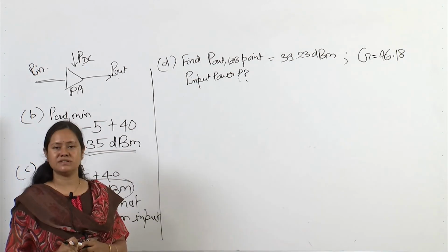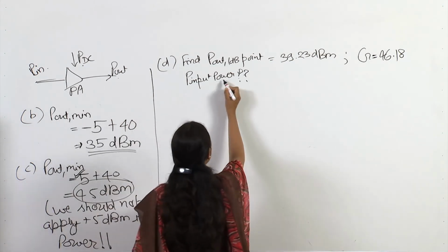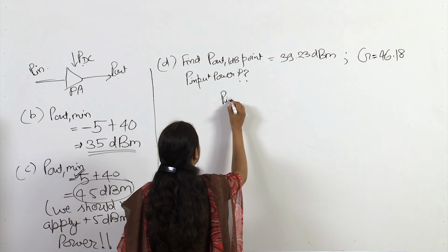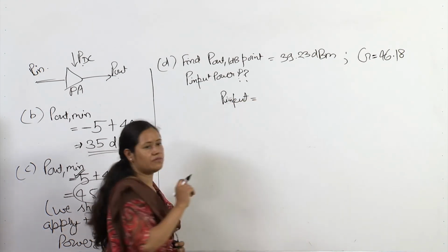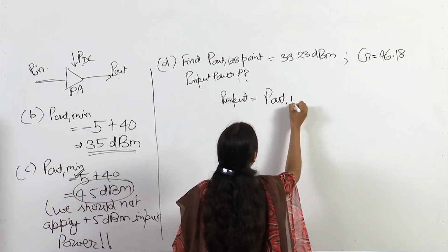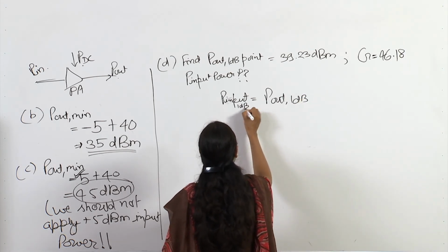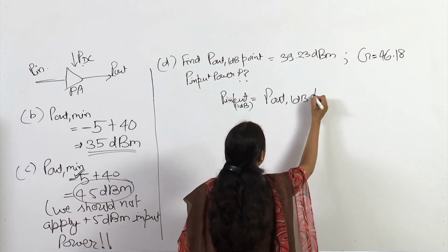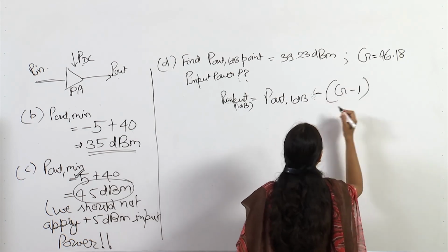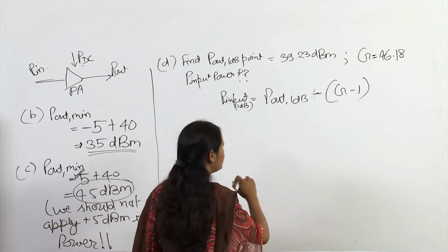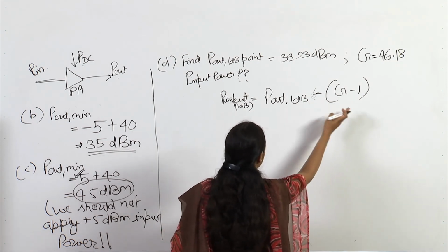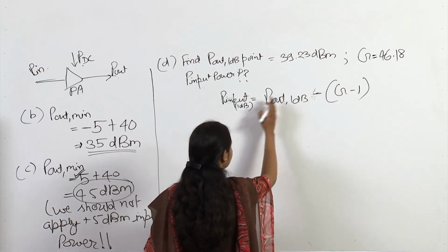So this is a small signal gain, linear region. When we want to calculate the input power, if you remember our formula for 1 dB compression earlier, it was P out is equal to input power at 1 dB compression plus G minus 1. So we do minus 1 dB here also. For calculation of the input power, we subtract this from this value.